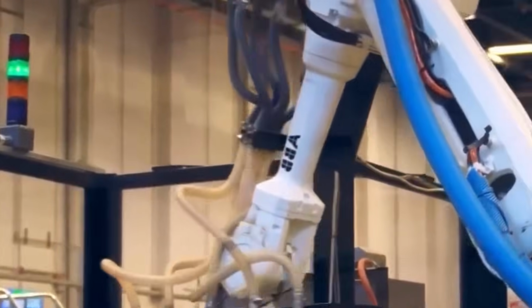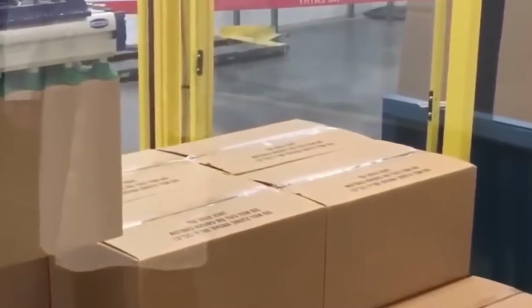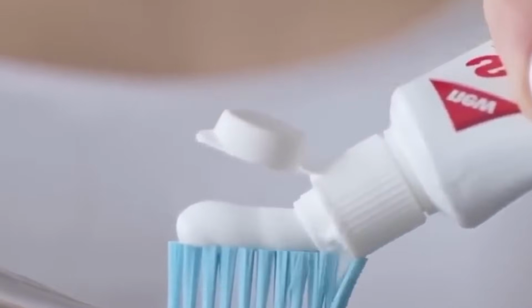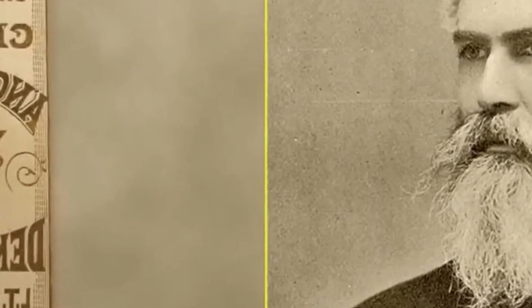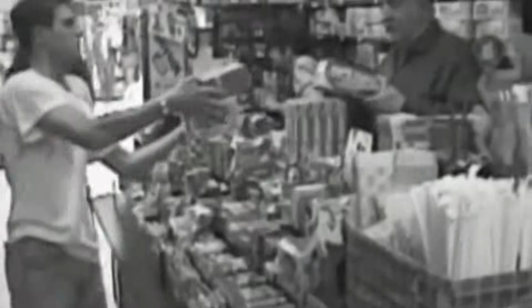Humectants, primarily sorbitol solution, glycerin, and propylene glycol, are stored in temperature-controlled, jacketed tanks. These are pumped into the mixer through flow meter-regulated dosing lines. The purpose of humectants is to retain moisture, maintain paste consistency, and prevent drying inside the tube. Viscosity and density of each liquid are tracked by inline sensors during transfer.